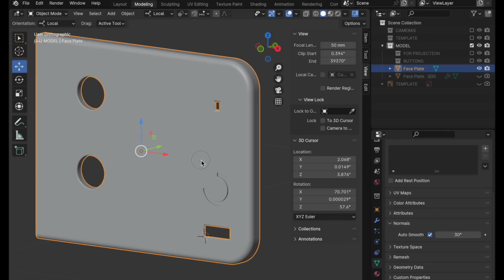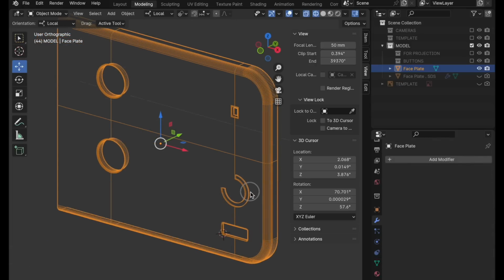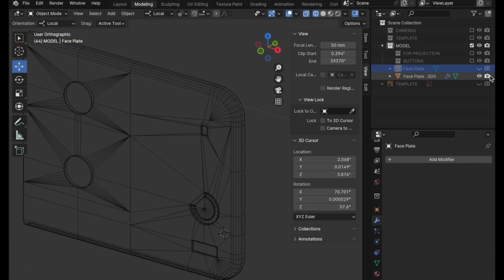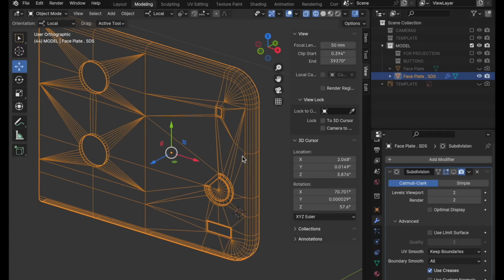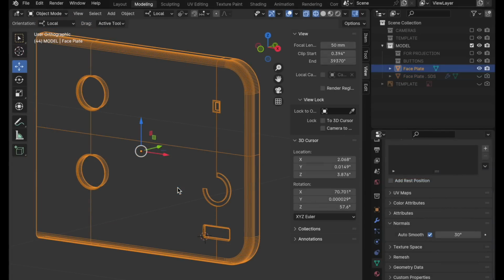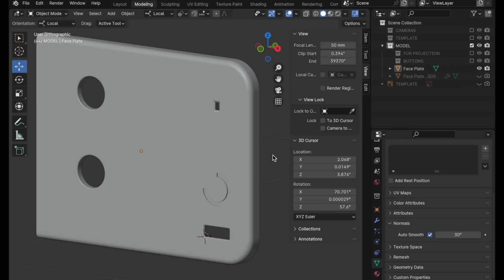So we have our faceplate modeled, and we've done it in such a way that we don't have to create a complex patchwork of polygons in this planar region to accommodate the subdivision surface algorithm. So in some cases like this, especially for mechanical modeling, a direct polygon approach may be a better way to generate a piece of geometry.